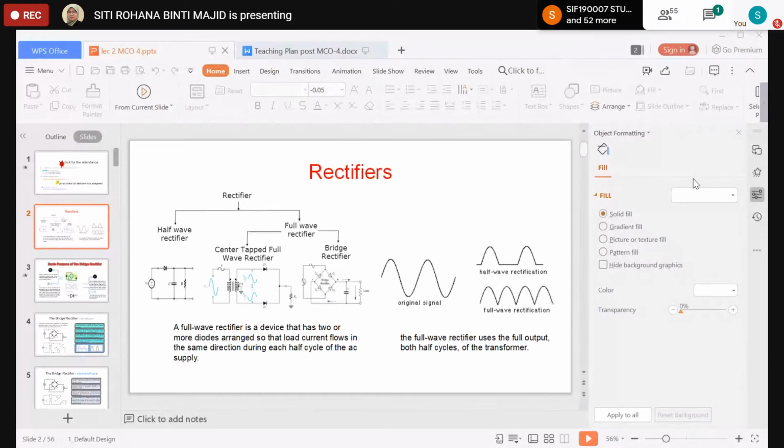The bridge rectifier does not use a center tap transformer. Because of this, the DC output is equal to the input voltage from the high voltage secondary of the power transformer. We can see from here that VP will have the same value as the input voltage. Also, the bridge rectifier can produce twice the voltage at the same size of transformer.